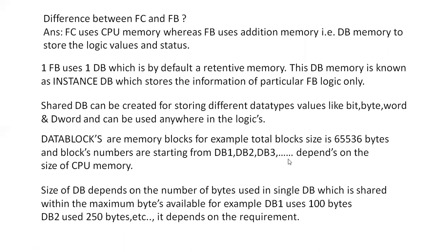So out of this total, we are using only 100 bytes for DB1, 250 bytes for DB2, like that, minus 350 bytes out of the 65536 bytes of total memory area. How much size you need, you can use from this total number of bytes. That's the thing here in the DB.